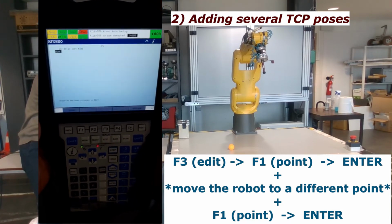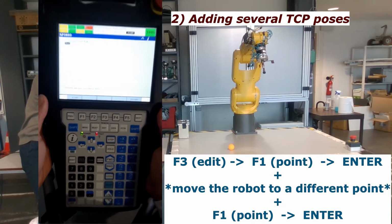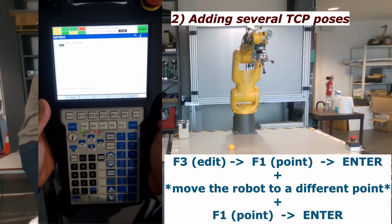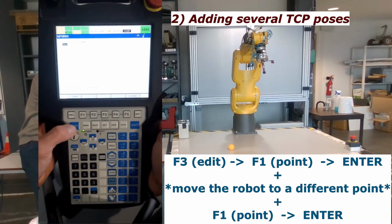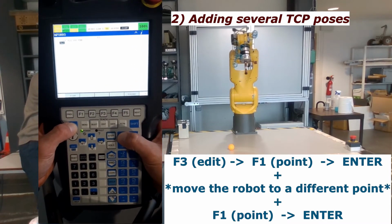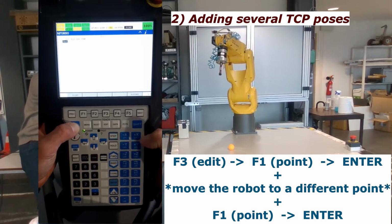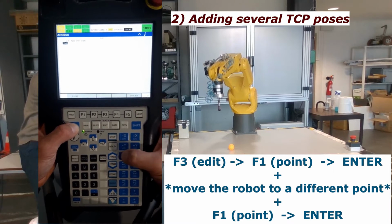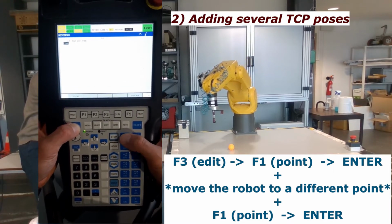We have now saved the current TCP pose as the first position in our program. I will move the robot to another position in order to record our second position. For moving the robot, do not forget to continuously press the deadman switch button and the shift key at the same time. We have learned how to jog the robot in the first tutorial.